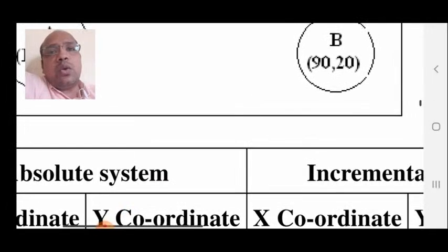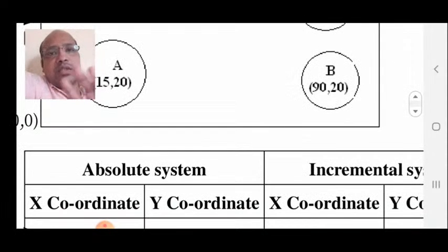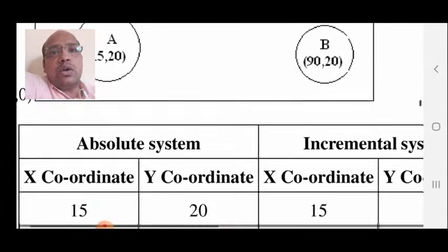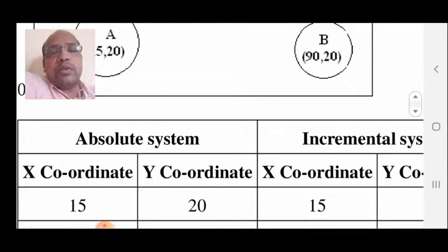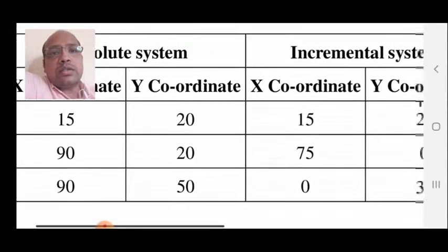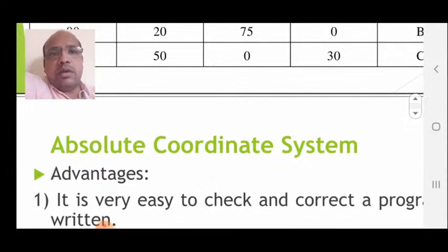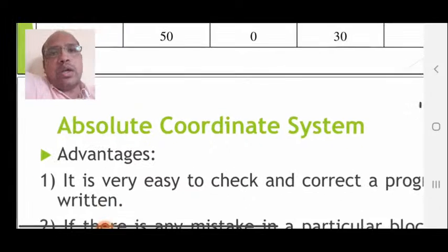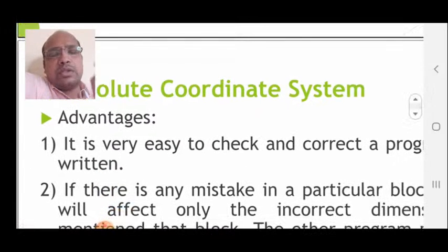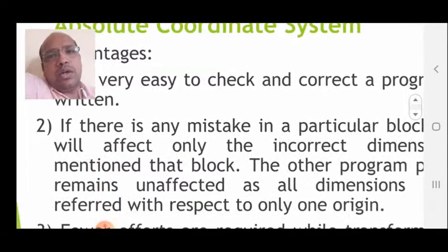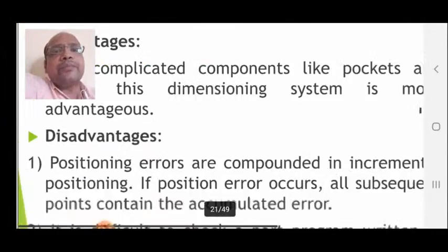So, I will say, it is quite risky to write a part program in incremental coordinate system. So a better way is to write a part program by using the absolute coordinate system. For that purpose, the G90 code is used, which is a preparatory code that we are going to learn in chapter number 8.